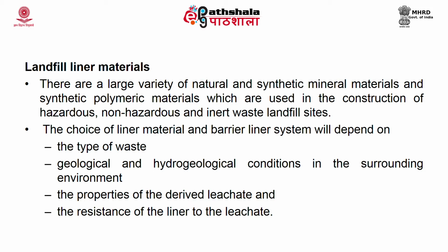The next important criteria is the property of the derived leachate. How toxic is your leachate? Sometimes these leachates are toxic as well as corrosive. These are hazardous liquids generated from hazardous material. They will possess properties like CRIT: corrosivity, reactivity, ignitability and toxicity.